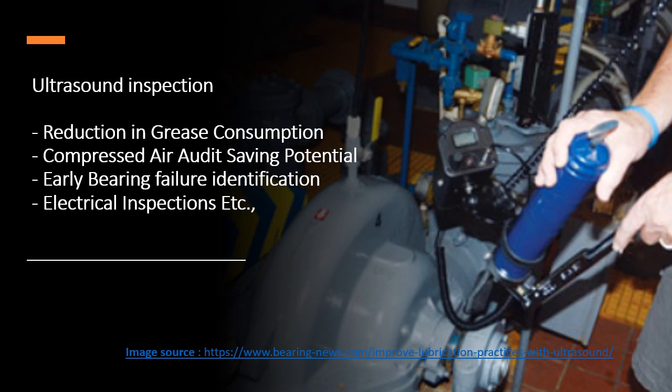In a typical manufacturing or process industry, the usage of compressed air is energy intensive. So you can use ultrasound technology to identify compressed air leakage, do an audit, and project the saving potential. Another thing to consider is early bearing failure identification. This is a very good tool to identify bearing failures at an early stage. If you already have a bearing monitoring program, you can compare the bearing consumption before and after the program.